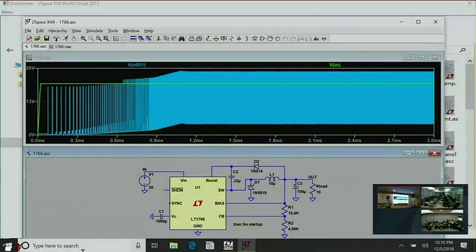But the topology of a switcher, you can ask that. So the first thing is, when they show you that schematic, don't look for the switches. It's a trap, because the switches might not be drafted. The switches might be integrated in some of the controller ICs they're using, and there you see why they've asked that question. They just want to see if you know what commercial products have integrated power switches and which ones don't, to see if you actually know anything about switch mode power supplies.